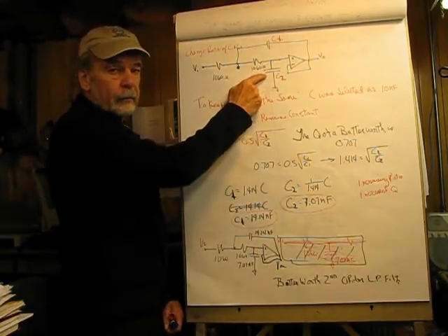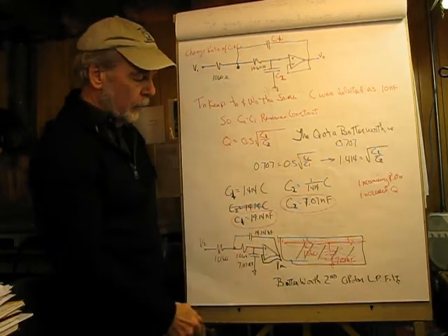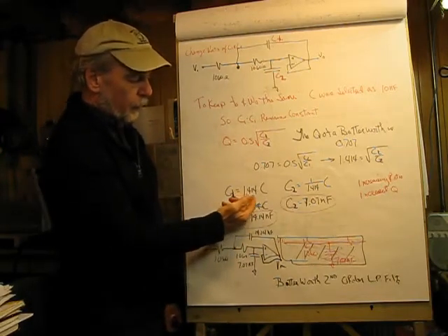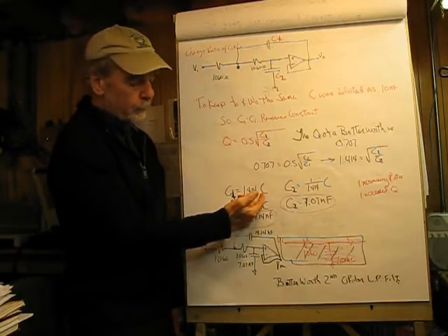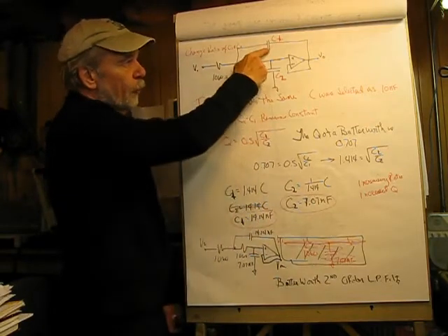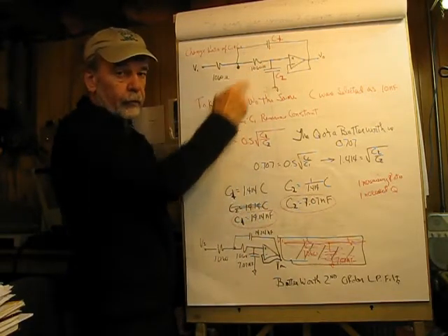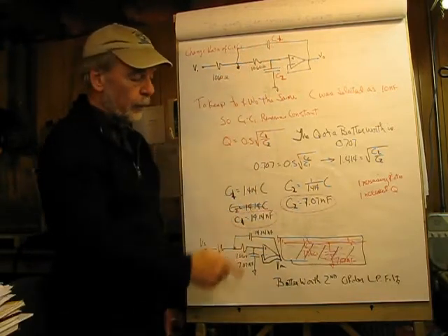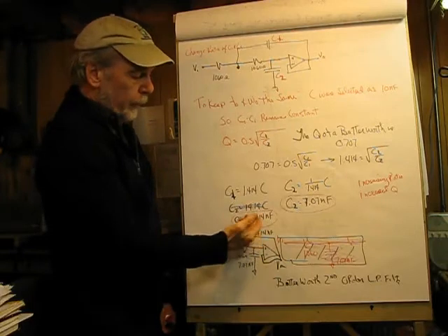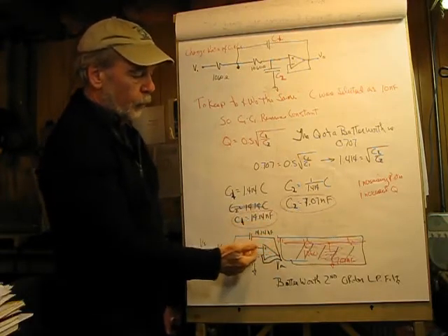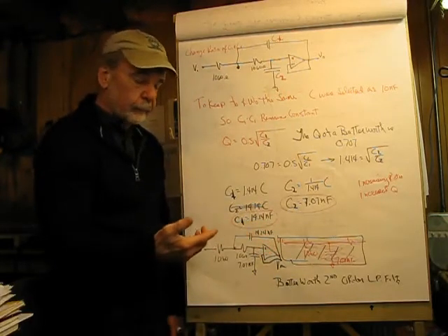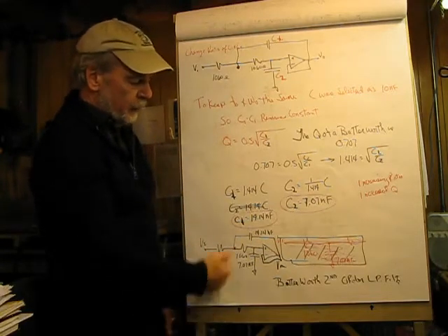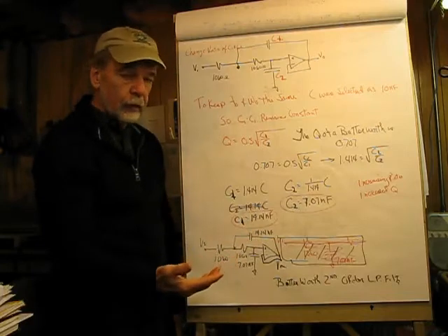That's this guy here. So he dropped in value. And likewise, C1, if we calculate him, is 1.414 times C. We end up with this as being 14.14 nanofarads, which, as you can see, is going to increase the feedback to this point. Now, what the books say about this is we're multiplying and dividing by a number that they call M and N. And in this case, I haven't gone through that step to introduce another variable.